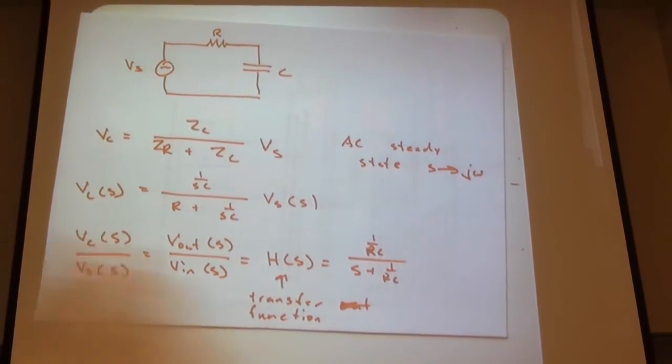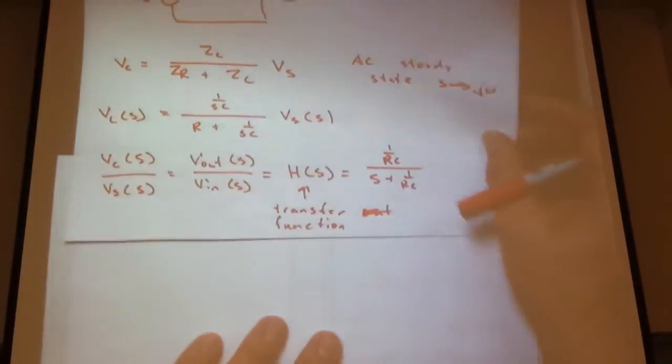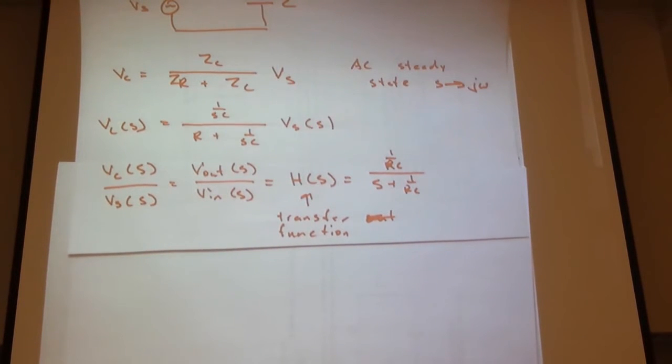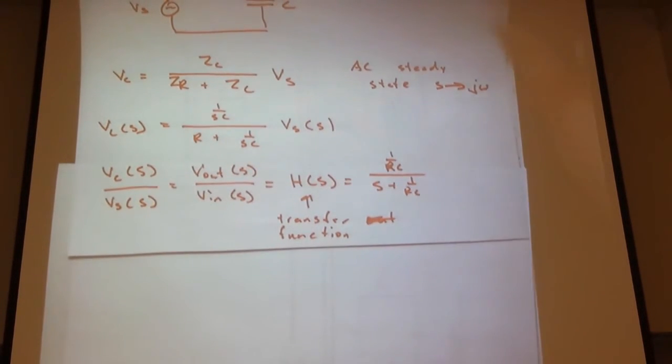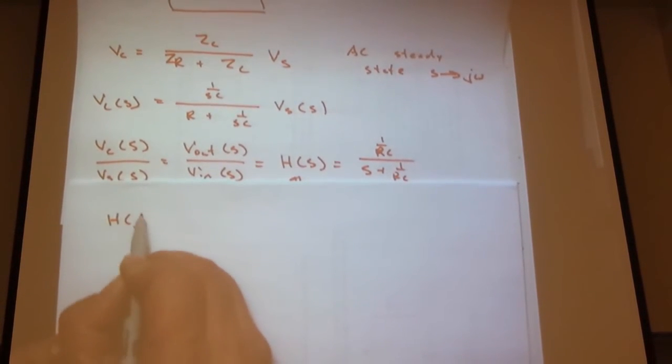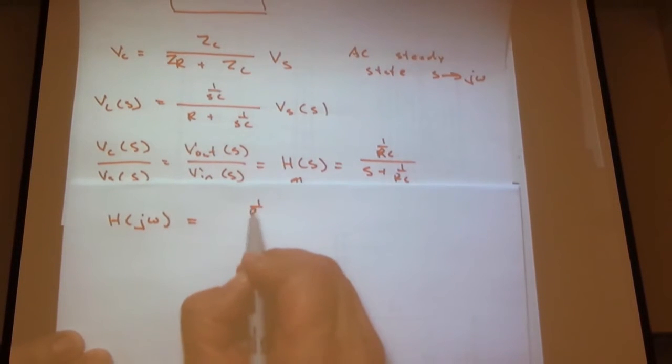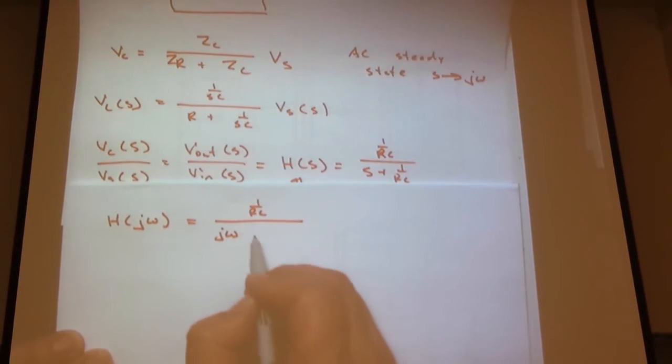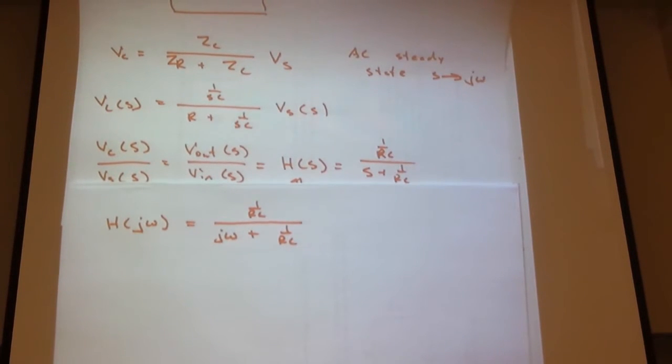Same thing we just did in that problem. You had a given frequency. If we wanted to look at multiple frequencies, we'd find our transfer function and then just plug in numbers using a calculator tool or something like that, so we didn't have to work very hard. Looking at this, we can write H of j omega for this problem equals 1 over RC over j omega plus 1 over RC. In that form, this is complex. R and C are numbers. Omega is a radial frequency, so it's another number. And so we can characterize it.